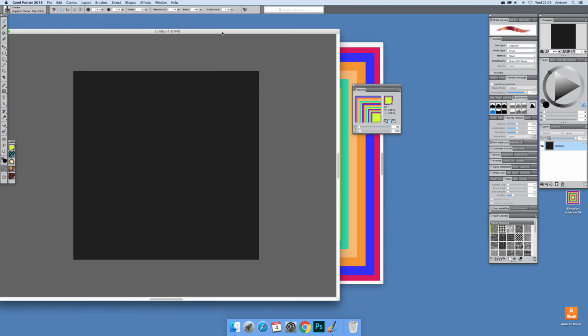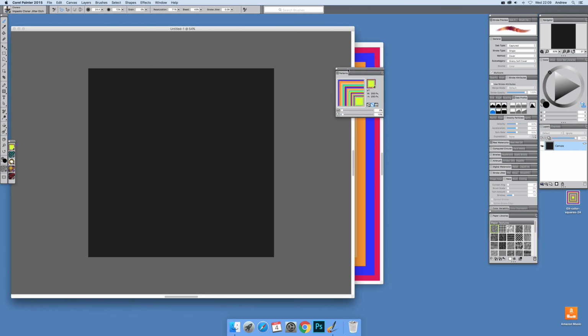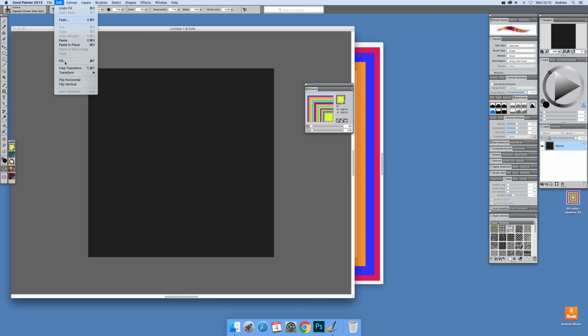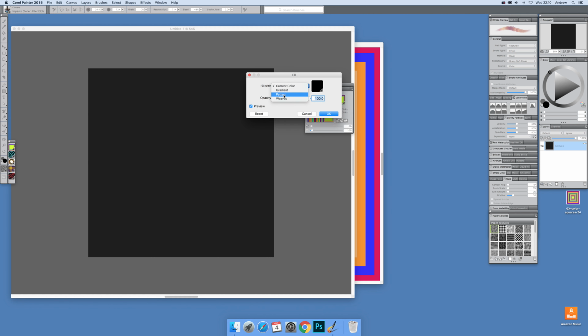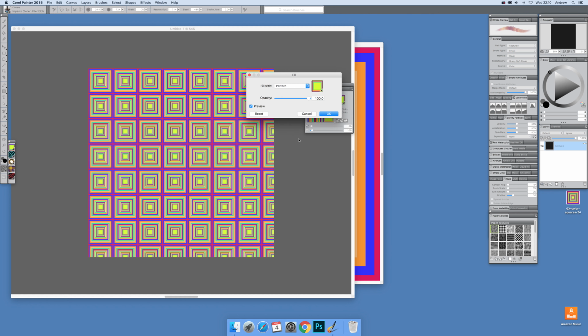I'm not going to use that document, I'm just going to use this one. This is not the pattern itself. And just set, there's 3 options. I'm going to go for the rectangular pattern type and keep that one set to 0. It doesn't make any difference. So edit and fill. Set pattern. And you've got the pattern design there.